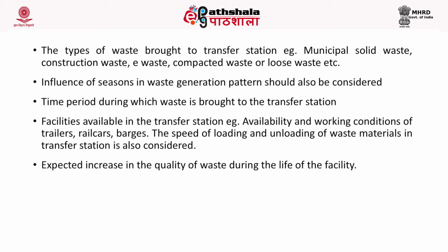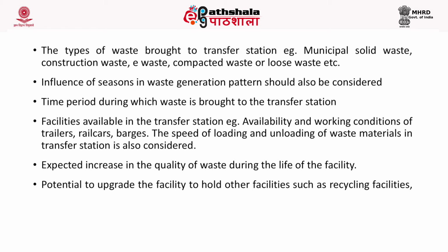Third, changes in the population, segregation pattern, recycling programs, peak flows of waste, types of vehicles delivering the waste, the nature of waste, for example, from which source the waste is coming, like the municipal waste, construction waste, e-waste, and so on. Influence of seasons, then the time period during which waste is to be brought to the transfer station, then facilities available in the transfer station, for example, the availability and working condition of trailers, rail cars, barges, etc.